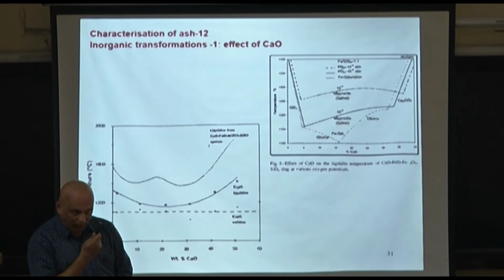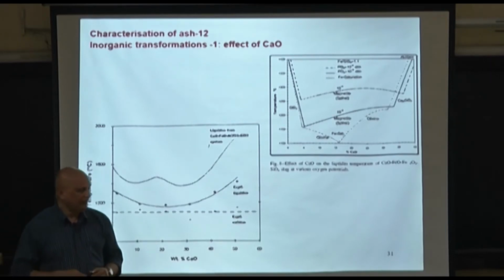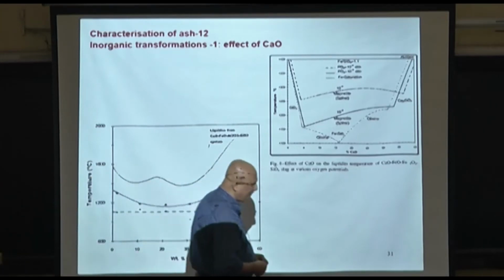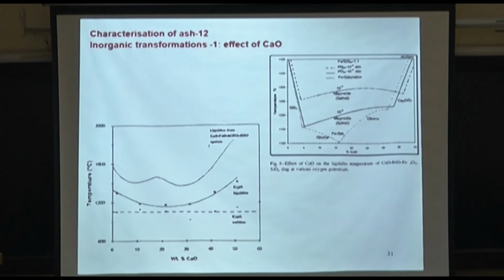So you really need to know where you have put the thermocouple's tip, and that it is kept quite clean all the time, not shrouded by a whole range of materials protecting it from giving the right signal. So, as a rule of thumb, in most cases, a thermocouple in this type of situation gives you the bulk gas temperature.